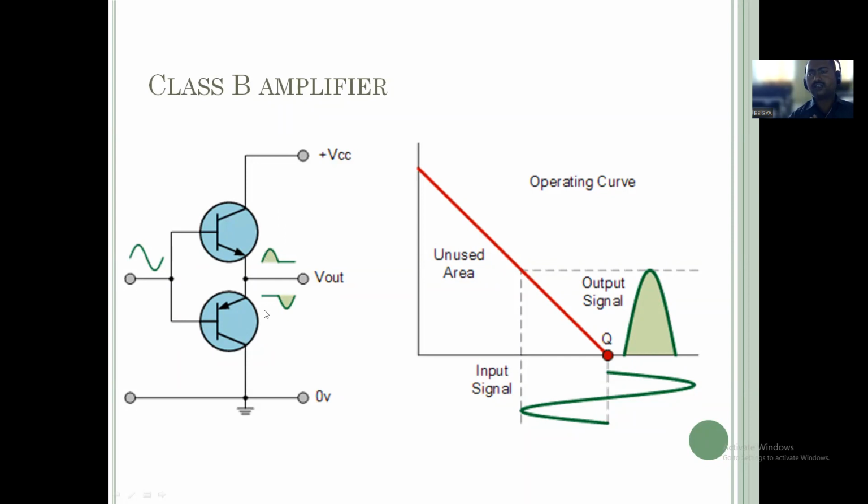See, we know that with respect to a diode, when we apply voltage, it does not work up to 0.7 or 0.3 volt. Why? Because that is called the cut-in voltage. All right. So up to that cut-in voltage, it will not work. The same thing happens with the transistor. It is also constructed from silicon or germanium. So due to that 0.7 volt, it will not work between plus 0.7 volt